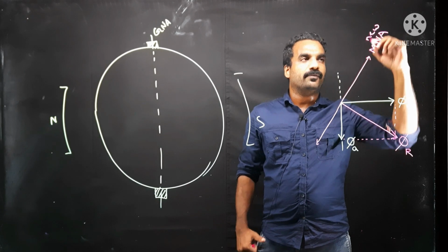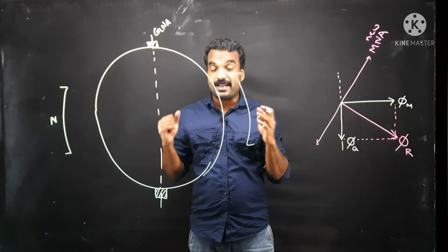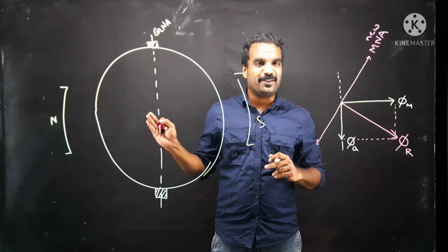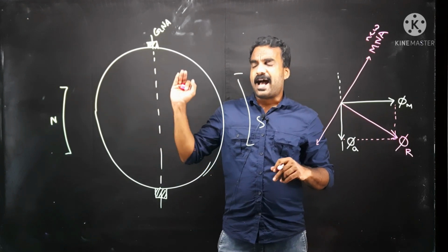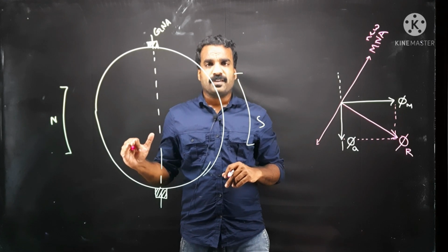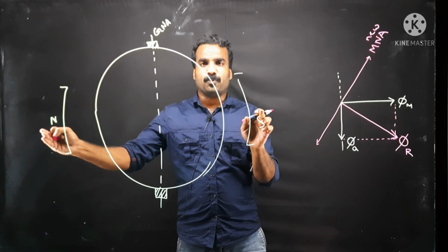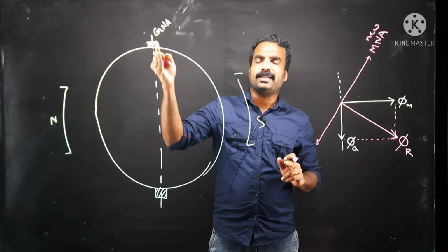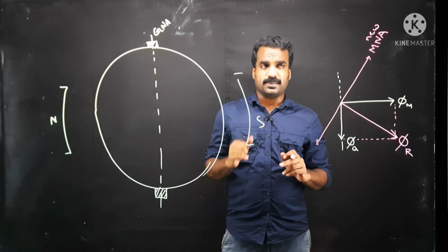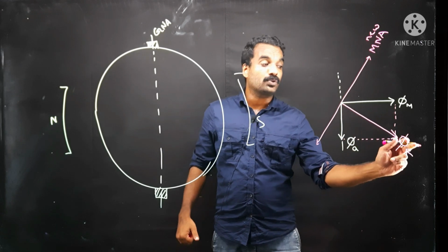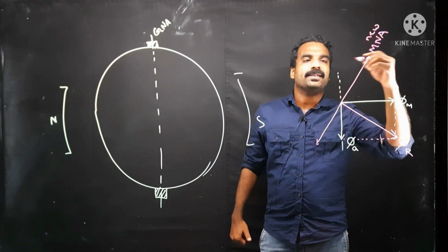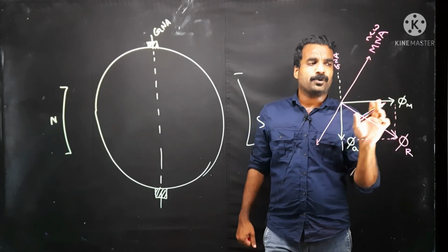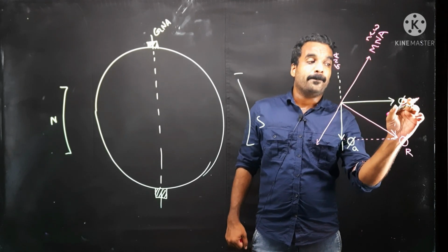Why is it new? Because as per case 1, please go back to the previous video if you have doubts, we considered only the main pole. So only main flux is present, so GNA and MNA are aligned together. But now we have a new resultant flux, so the MNA will shift, but the GNA will stay in its original position, because GNA depends only on the main flux.